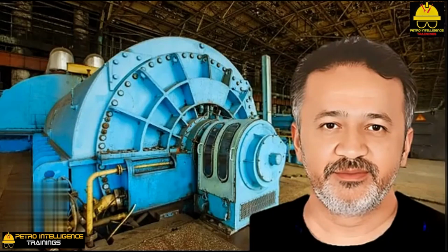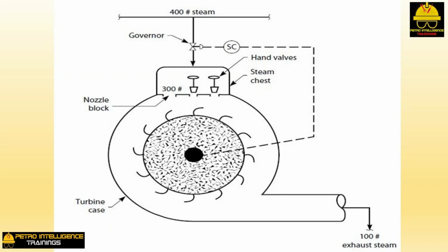Speed valves. This picture shows a steam turbine with 3, rather than 1, nozzles. The single, largest, left-hand nozzle is called the main nozzle. It handles 60% of the motive steam flow. Each of the two smaller nozzles handles 20% of the steam. These 20% nozzles can be plugged off by a device sometimes called a horsepower valve, jet valve, speed valve, star (for the handle shape), or port valve.